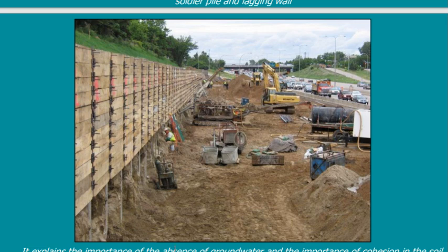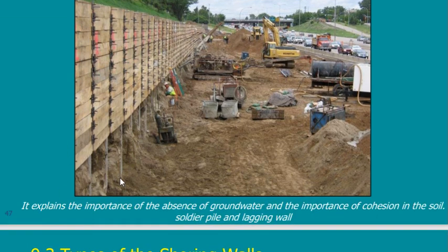So what we are going to do is that this is soil, this is rock. I drill holes here in the soil and penetrate the rock, and then put the steel section, and then pour concrete till the rock level, and then leave the wooden lagging alone in the soil. So when I drill in the soil, I start putting the wooden lagging one by one till it reaches the top of the rock, or it may penetrate a little bit in the rock. Then I stop pushing these wooden lagging below, because I cannot push them further.